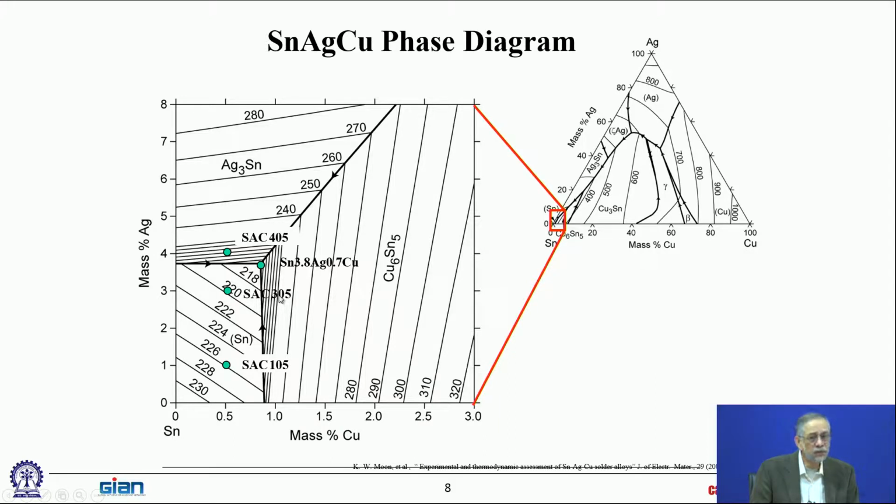Okay, so SAC 305 is extensively used in the so-called high-rel industry: harsh environment, automotive, aerospace. They all use SAC 305. The portable electronics industry found that SAC 305 had very poor drop durability. It has good ability to survive temperature cycles, but doesn't do very well in mechanical loading like vibration, shock, and drop.